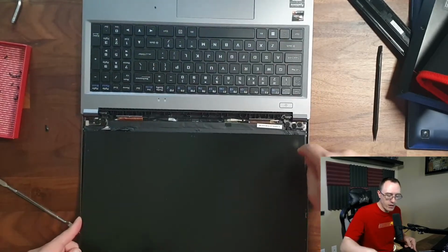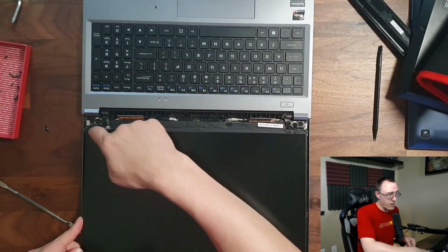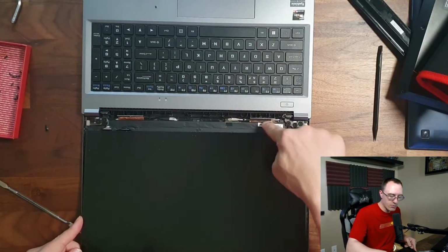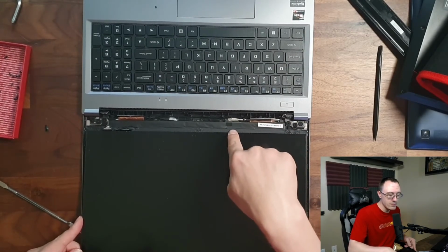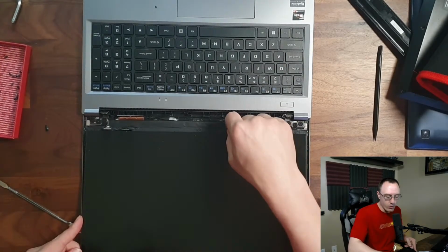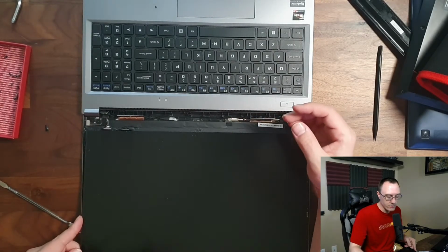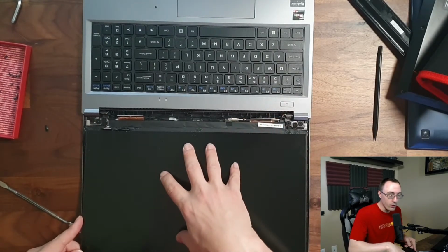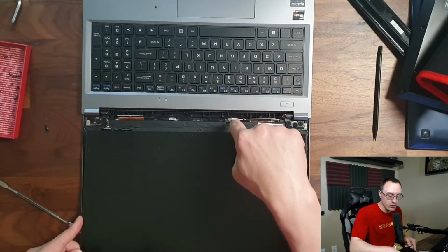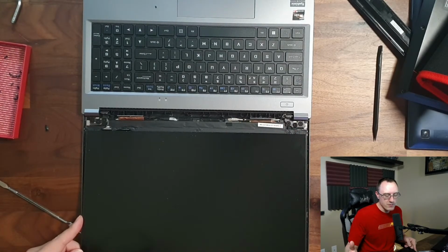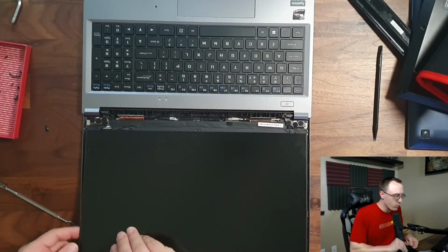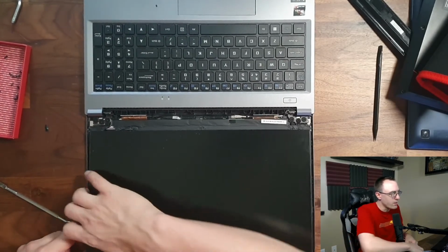You want to be especially careful if you're going to be prying around the base here, because you have the video cable that's running up through here, and this video cable is connected usually with some sort of adhesive on the actual LCD. If you pull too hard, you can break the connections, which isn't a big deal if the screen is broken, but if you break the connections on the actual cable itself, then you got to replace the cable. Those aren't expensive, but it's nicer to only replace what you have to versus having to pay a whole bunch more to replace things than you need.